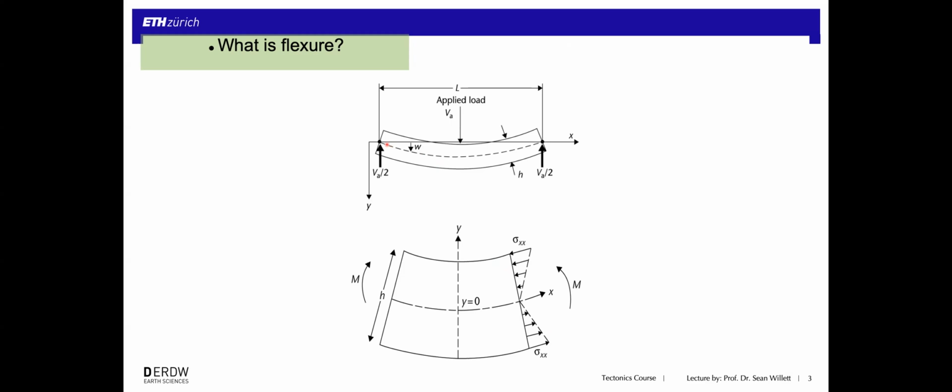So this problem, in fact, has been simplified. The simplification is to a thin plate, where it's argued that even though the load is vertical, the stresses are going to respond only in the horizontal direction. And the reason they do this is because the stresses are dominated by a bending or flexure of that plate rather than by the vertical loading. Normally, if you put a load on a solid, you'd think most of the stresses are going to be directed downward, right? We have a sigma Z that's pushing down on the plate.